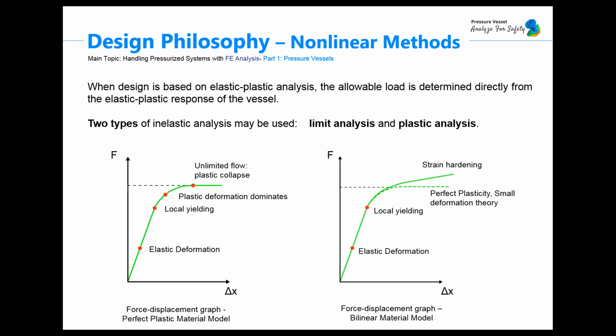However, real structures may behave differently from the limit analysis model in two ways. The material may exhibit post-yield strain hardening and can also exhibit large deformation. As strain hardening materials can support stresses greater than yield, plastic deformation can continue for loads above the theoretical limit load of the structure without violating equilibrium.